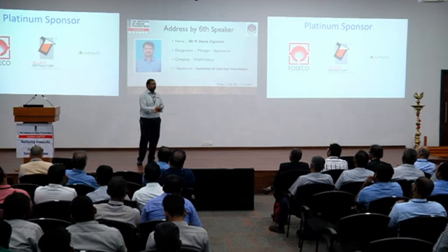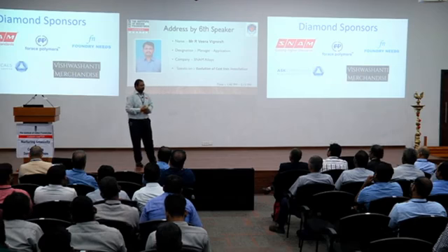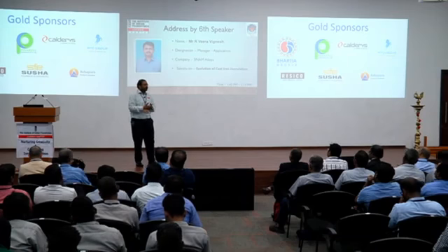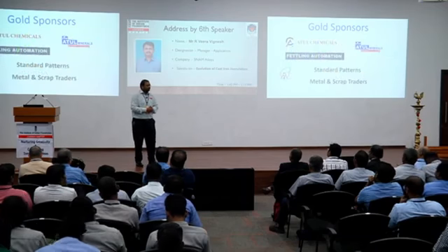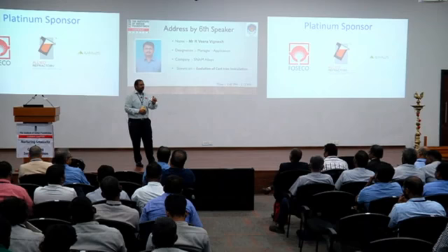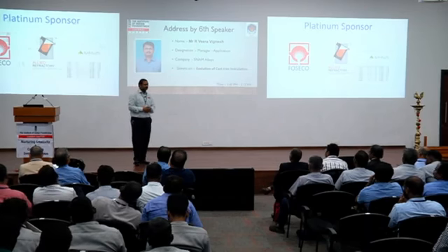Amount of dissolved oxygen I can tell directly, but there is no measure right now available, sir. So it has been arrived at by different trial and errors, and an inoculant with less than 0.5 aluminum, there is no existing inoculant like that. So it is like silicon is balanced by calcium, silicon calcium is balanced by aluminum, and this combination gives you some effect. So it is arrived at that level, sir.